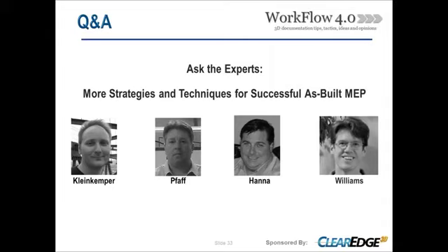Mark, this question is for you specifically. When you're using a C10 and a Faro Focus to do the hospital, what software do you use to complete your registration with the two different scan data? We typically stay within the scanner software. So for the Faro, we're using Scene to do our registrations, and for the C10, we'd use Cyclone.